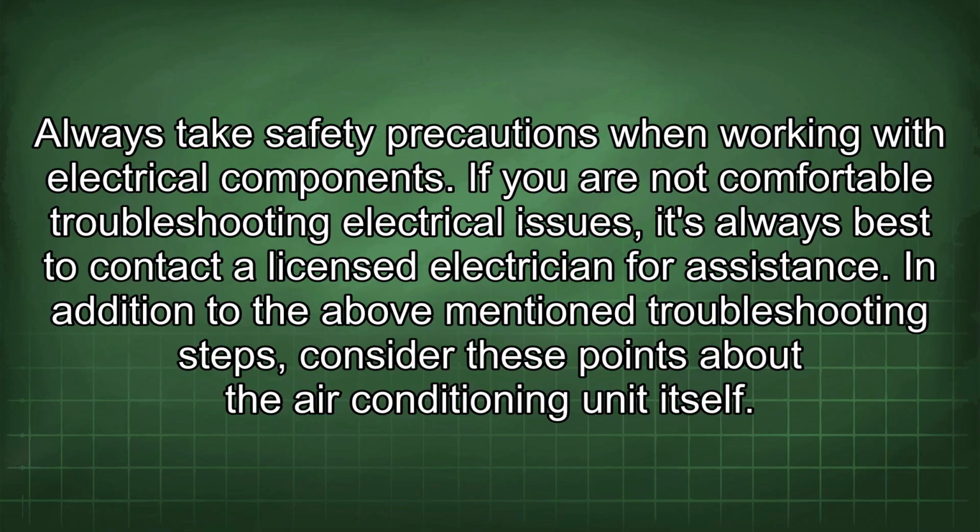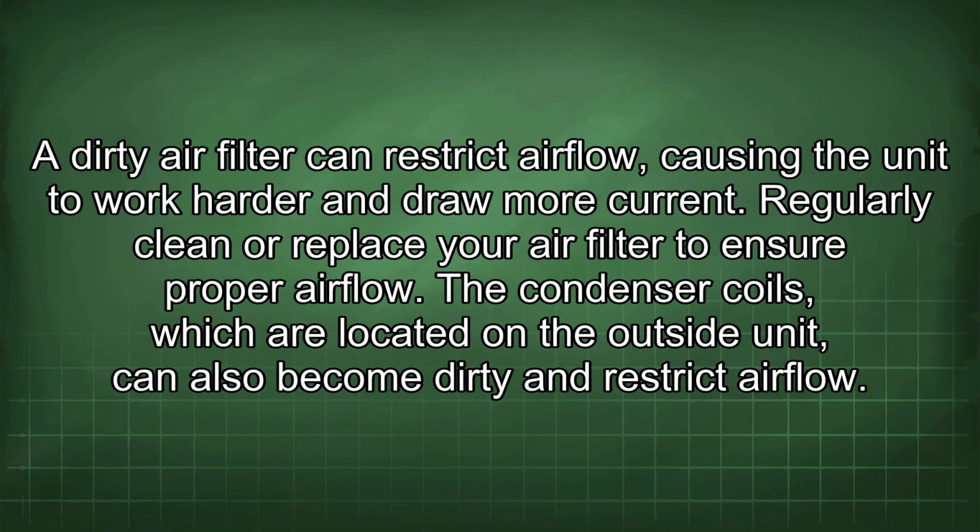In addition to the above-mentioned troubleshooting steps, consider these points about the air conditioning unit itself. A dirty air filter can restrict airflow, causing the unit to work harder and draw more current. Regularly clean or replace your air filter to ensure proper airflow.